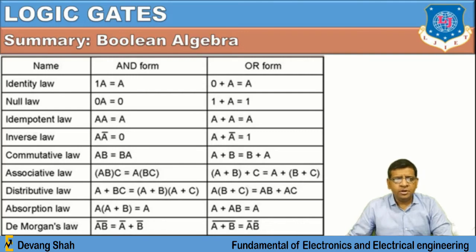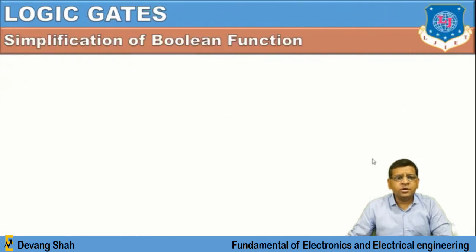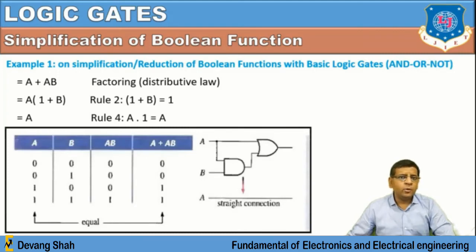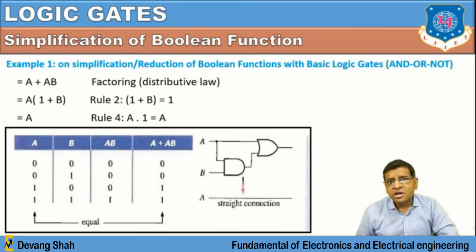So you use this particular De Morgan's law, and from that you can apply a kind of simplification of all the Boolean functions like A plus AB, where you apply all the rules and you get A plus A bar, that is equal to A. Now what is the importance? See, you have a large Boolean function, that means you have large digital operations. If there are more variables, more literals, and more operators like plus, dot, NOT, you require more gates, right?